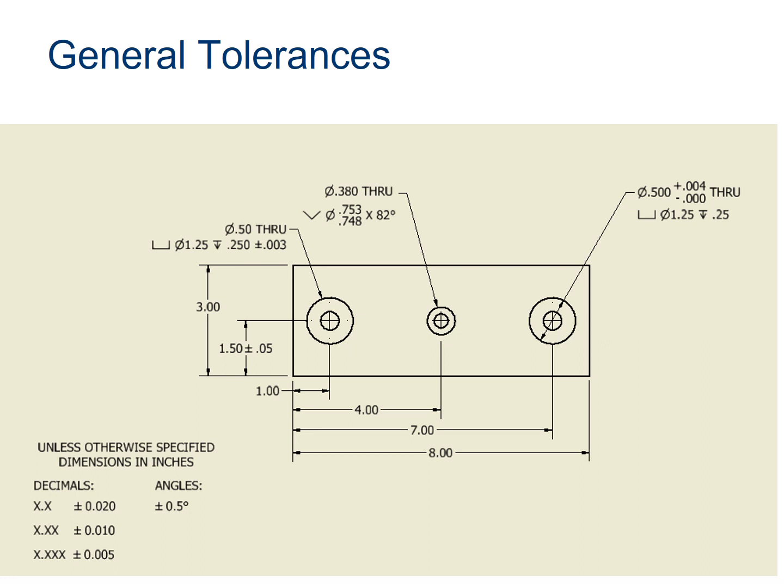If you'll notice, this particular part right here is that drill block that you did a sectional view on earlier this week. So there's your specified dimension there. What would be the acceptable variation? Well, I've got 3.00. So my general tolerance that would apply would be right there in the red circle. X point XX plus or minus 0.010. That means it can go up or down by that much.